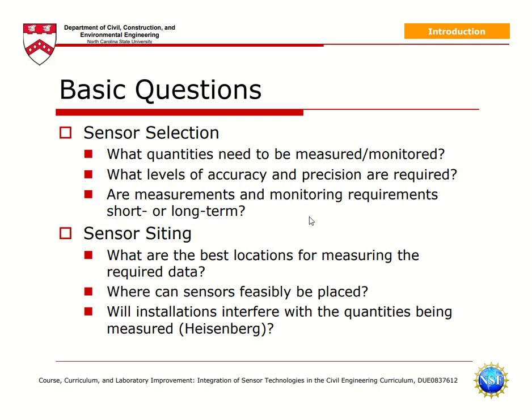Sometimes what happens, you've decided that the price of the instrument is this much, then the price of the sensor is this much, but the installation and the setting of the sensor requires more than the cumulative sum of both of them, so that is not feasible. So you have to identify the correct physical position where the placement of the sensor becomes feasible. And then the final question that you need to ask, will the installation interfere with the quantities being measured or not?